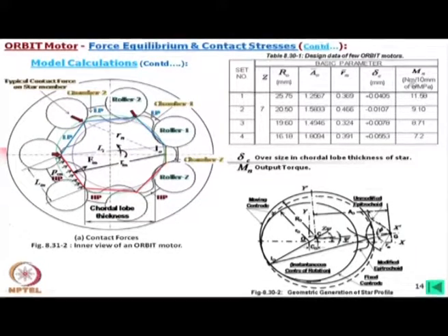This is in Newton meter per 10 millimeter of width per megapascal. So, suppose you have 15 millimeter, you simply multiply by 1.5, and for a pressure of say 15, 1.5 into 15 into this will be the ideal output torque of such a machine.